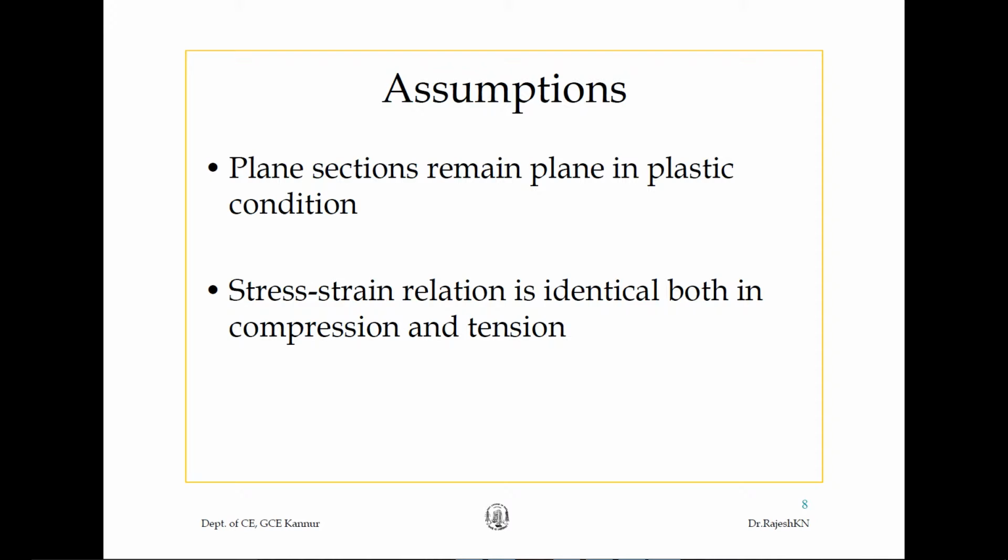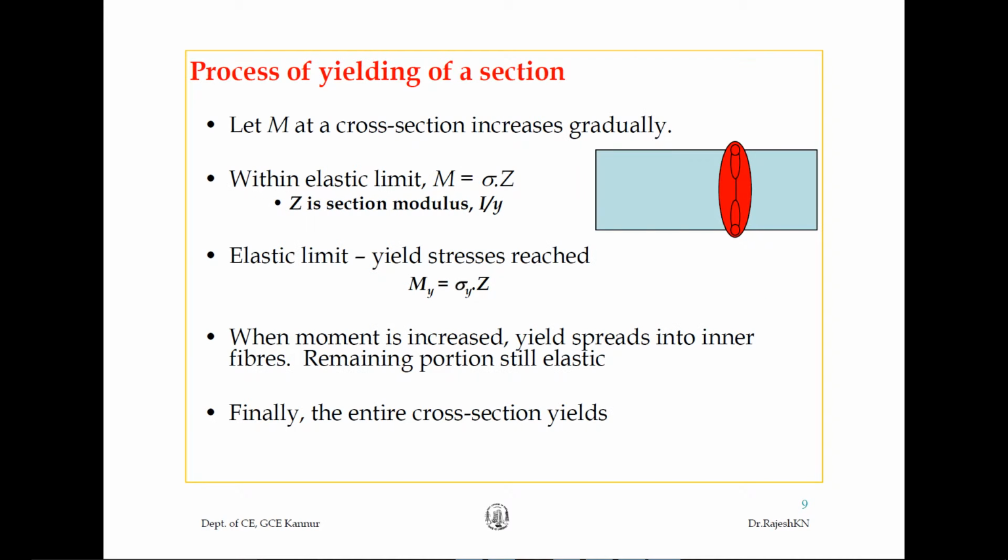Now, some of the assumptions we take in plastic analysis are: a plane section remains plane in the plastic condition, and the stress strain relation is identical in both compression and tension. That is normal: the compression and the tension in a flexural member will remain the same.